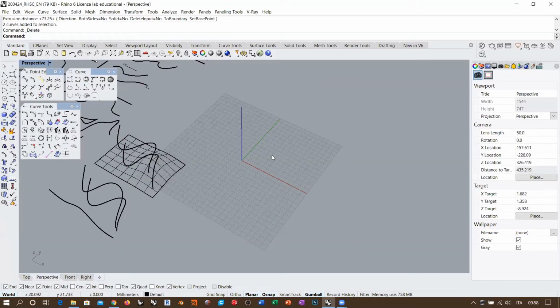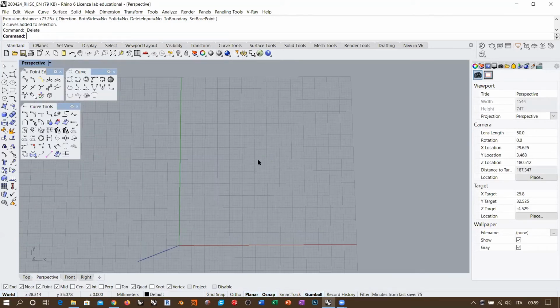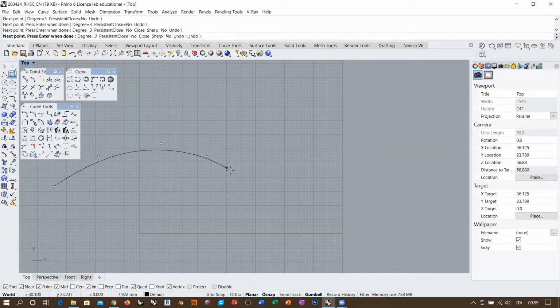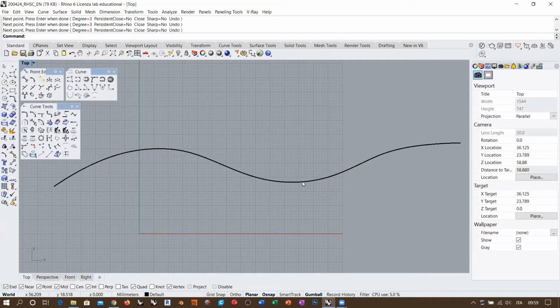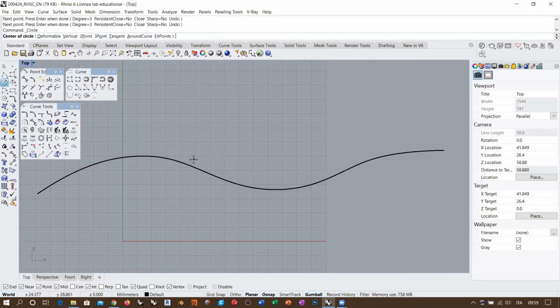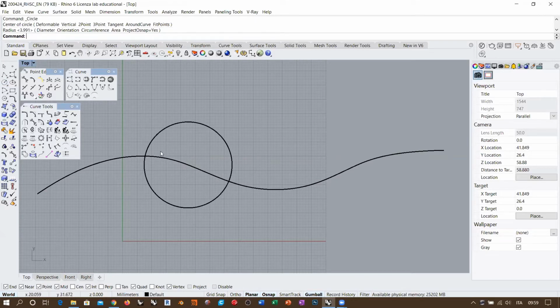This is when you want to do the rebuild of a curve, okay? Let's see when you don't want to do the rebuild of the curve, which is the more important part. So, for example, let's say that I am modeling something, and then I get this kind of smooth curve. Remember that everything we are saying also affects surfaces, so we are going to find this also on surfaces. Let's say that inside this region here, we want to create some kind of local deformation, I don't know, toward the inside or the outside of this curve.